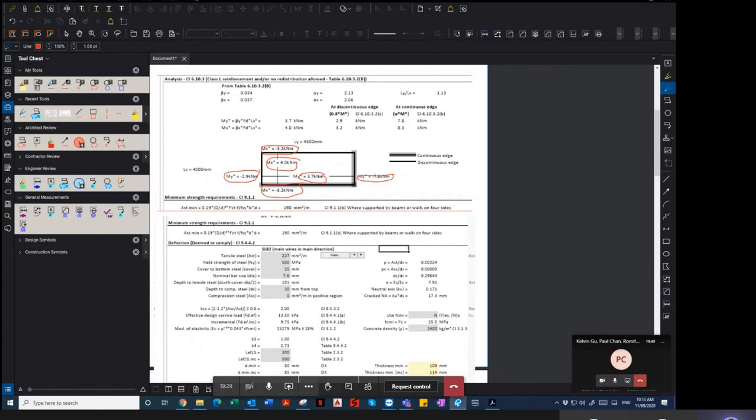If something in the middle of the slab is 3.5 by 5 meters, we know it will work because the worst case has worked, and we all have to do this once or twice in our lifetime to have that confidence that that's how the slab behaves. This is how the moments are distributed, and I've done it once, and I know that a 4x4 slab works. It's like building confidence.